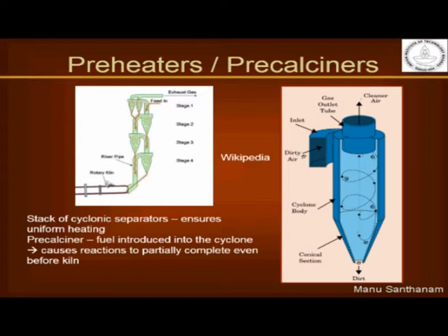Okay, so now you get calcium oxide at very high temperatures. Now what if these high temperatures are reached within the pre-calciner itself? That would further reduce the amount of time that the material needs to spend inside the rotary kiln, right, because part of your process is already complete. So that's why most modern cement plants tend to employ what is known as a pre-calciner, where some amount of burning actually takes place within this preheater tower itself.